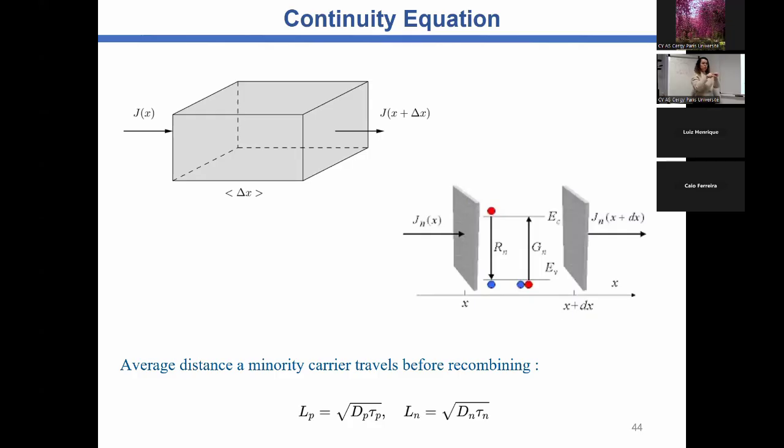With two points you can just put them on your sample, and you can hear if it is continuous or not. If it is continuous, you will hear one beep. If it's not continuous, you will not hear anything.